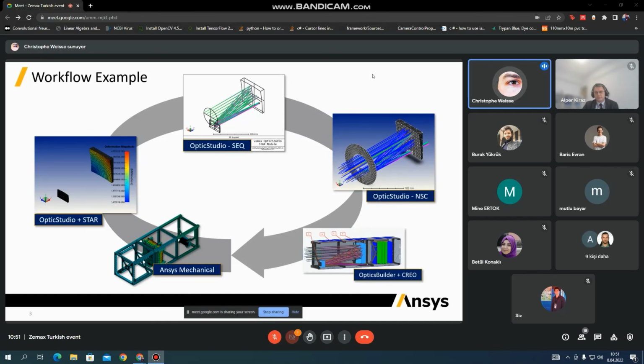Speos already had the Speos lens importer that uses Zemax ZMX or black box files as a reduced order model in Speos simulations. We also had options to communicate with optiSLang, another ANSYS product for system-level optimization, so you can connect different simulation tools and optimize on the best combination between all the different physics.